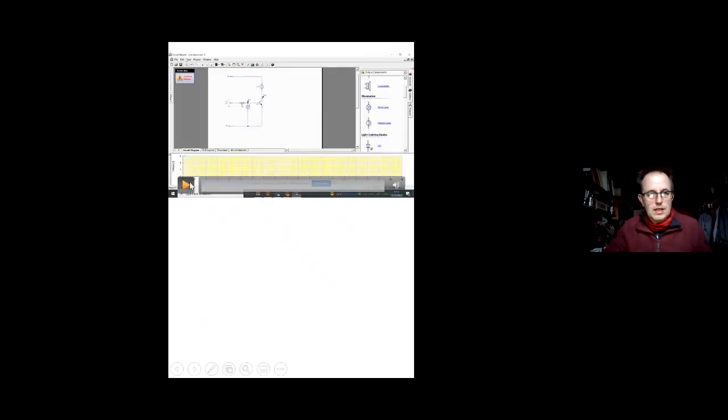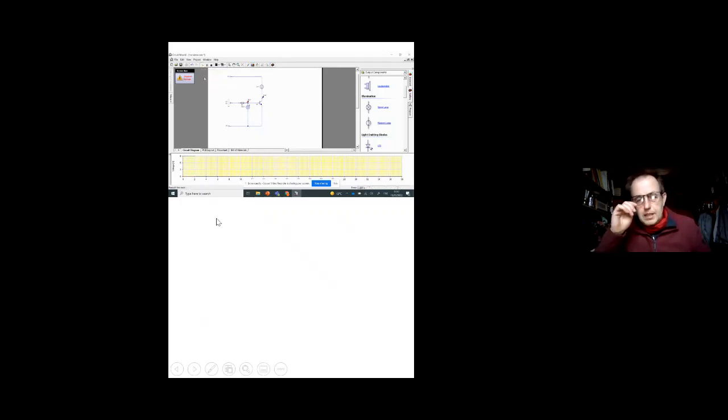So let's have a look at a transistor in working order. In this case, the input voltage is going to be changed, and that is the red line you're seeing there. Once that has reached 0.7, at this point, the transistor has started to turn on. So you're seeing the output voltage of the transistor decreasing.